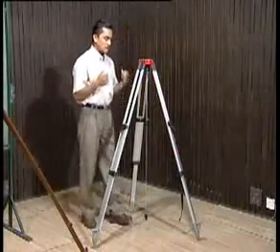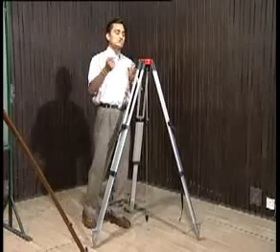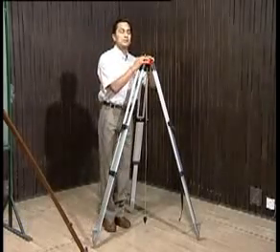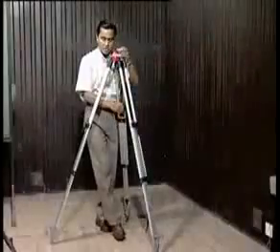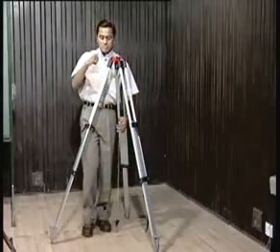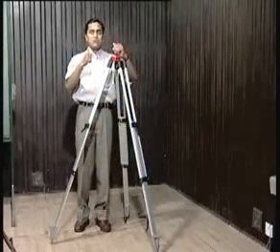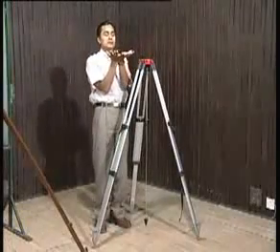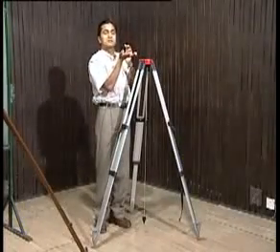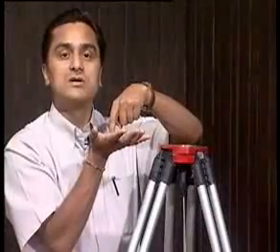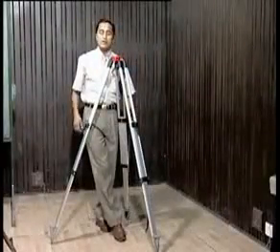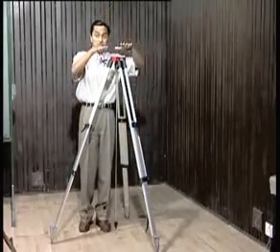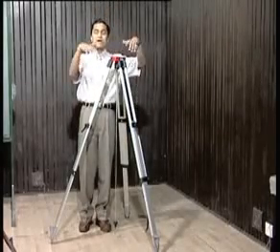Now what my job is, because I need to measure the angle A, B and C, so I want to put my theodolite in such a way that the vertical center or the vertical axis of the theodolite passes through the point there in the ground. Because the center of the theodolite means where, when I rotate the theodolite in horizontal, it is rotating about an axis. That's the point which is the origin, about which we are measuring all the angles. So I need to bring that vertical axis of the theodolite over that point. And our theodolite has to be vertical. At the same time, the horizontal plate of the theodolite has to be horizontal.